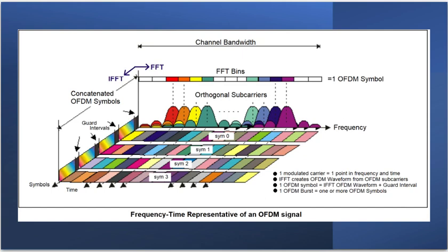When you do FM or PM, you can literally operate the amplifier in compression because all the information is not in the amplitude, but the phase. So that's an advantage of FM broadcast. They can operate those amplifiers in compression. They'll have to put filters after it to suppress all the spectral junk, but they can get the most power out of that amplifier because the content is not in the amplitude of the carrier, but the phase. That is not the case for OFDM.